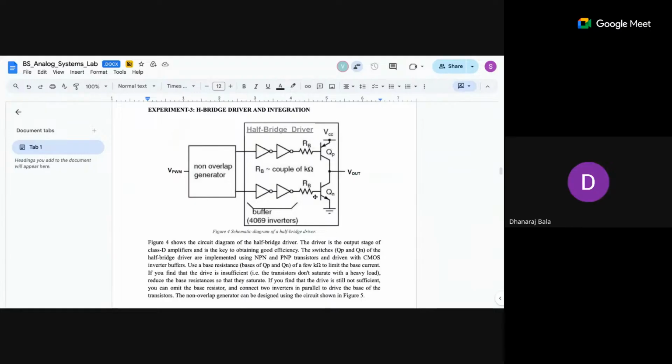So to have the same configuration, we only need to change the transistors. What should we do? In one branch you have an even number of inverters, and in the other branch an odd number. So here, instead of two, you just put one inverter.